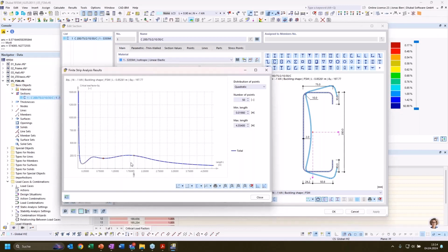the member length. So we can see that in the start, we have a very small member length. In this case, for example, the first minimum is evaluated for a member length of 14 centimeters, which would be the smallest column stub that we have just investigated with our shell model.